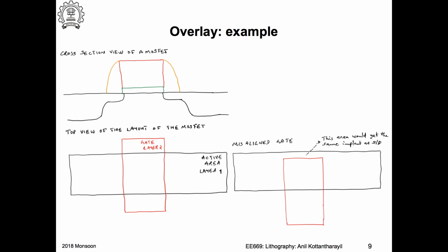Okay, this is a top view. So this is my silicon exposed, and then I have my gate. The gate will be a strip like this, right? Got the point? So this is what is called the active area. If I take this, what is surrounding it? Isolation. So we have this shallow trench isolation and all these things, right?